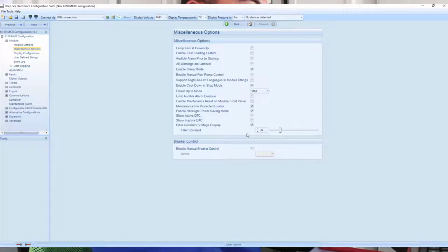In the DSE, it is stable, but in reality, if there are fluctuations in your voltage and you use a multimeter, it is still fluctuating. This is only to hide it in the module in case of some emergency. So for me, this is not important in order to know what the real problem of your voltage is.